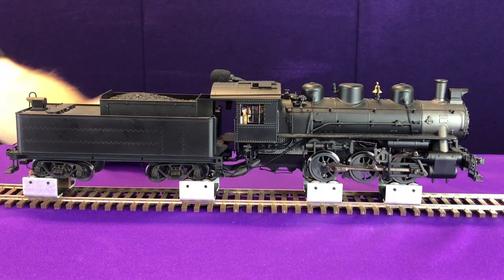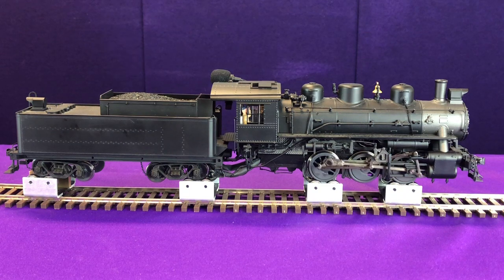Now the last step, you've got 3 sets, and then the fourth turn on the F5 goes into drifting mode. You'll hear the snifter drop, you hear a leaky valve packing, and now you're basically just hearing the rod clank. And this will run this way as long as you have it. So regardless of the speed step, I can increase or decrease my speed, and you will never hear that chuff because now we're fully drifting.